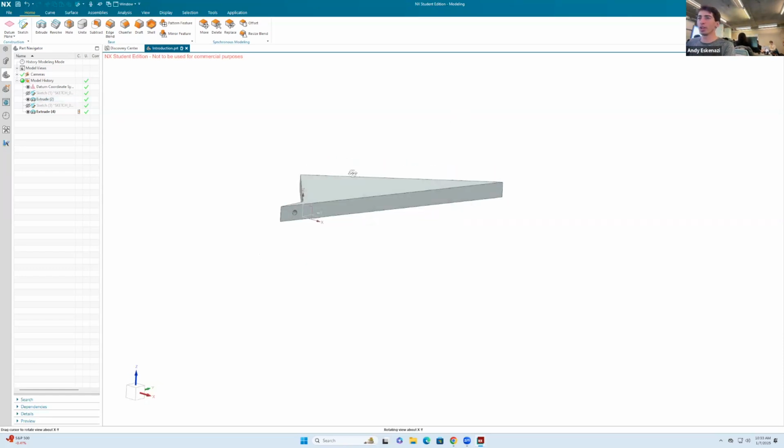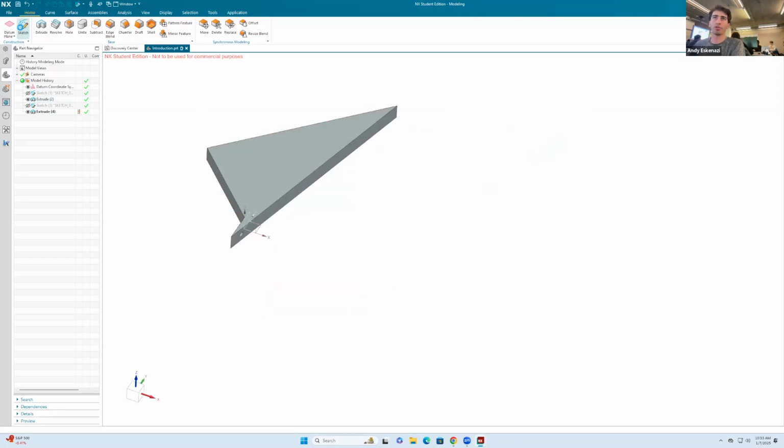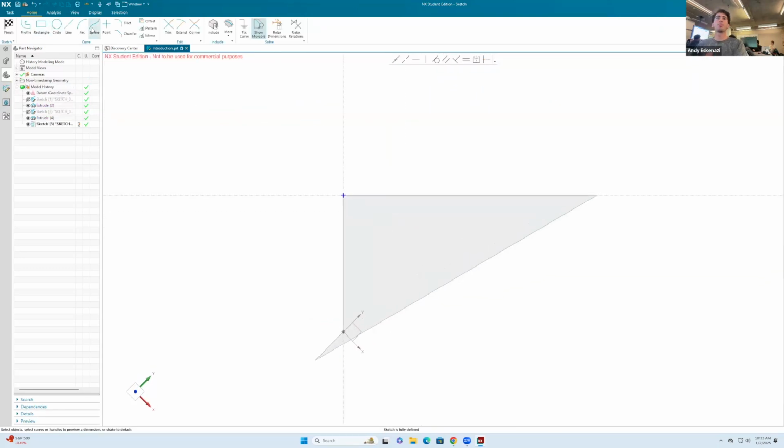But just a couple more things that you can do before you start playing around is that now, for instance, we can go back here to sketch. We can do a sketch here on this particular face right there. And let's explore other things. What are the different commands that you have available in here? Normally, I'll give you a taste of the ones that I would never use, actually. So whenever in sketch mode, I would never use fillet and chamfer. Never use those. I know it's available to you, but one of the best CAD practices that I learned from people that do design, like literally design engineering, is to never use those two. But those two are actually available afterwards as features if you need them. And I'll explain what that means in a moment.